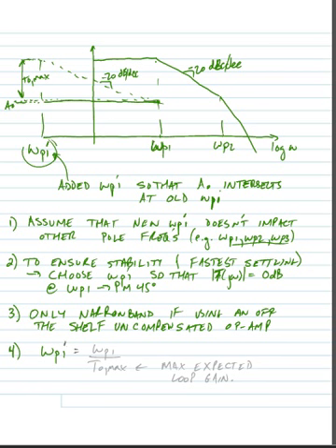It would be equal to omega P1 divided by whatever our maximum expected loop gain is. Okay, so in the next part of the lecture we'll look at an example of a type of narrowband compensation and see what you might do if you were designing for narrowband compensation, though as I said before we'd probably never use narrowbanding if we were designing our own op amp.